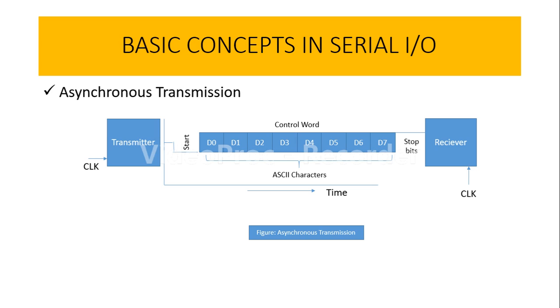Okay, here each character is going to carry the information about the start bit and the stop bit. When there is no data being transferred, the receiver is going to stay at the high, that means at logic 1, which is called mark, and logic 0 is called space.